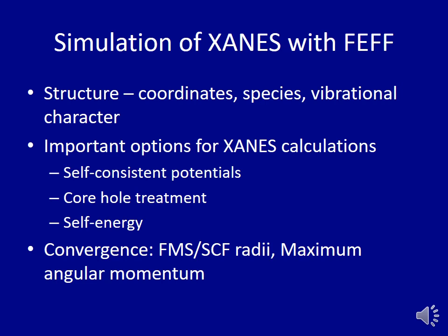So you're going to hear a lot more about this, but I'll just briefly go over what it takes to simulate XANES with FEFF. The basic idea is that you have some input structure. You need to have coordinates, species, vibrational character possibly, and that's the input for a XANES calculation or an XAFS calculation in FEFF.